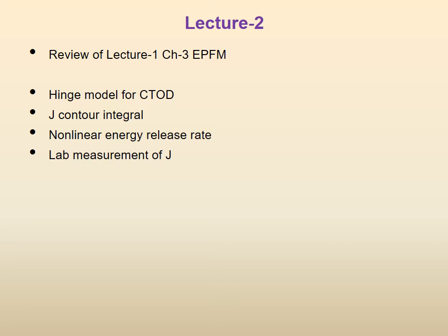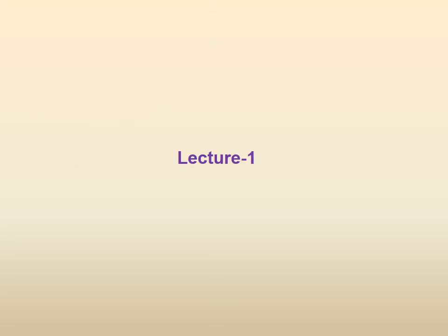We will of course start with a review of the previous lecture, and today the topics we will cover: we will continue with the hinge model for CTOD that we started last time. Then we will talk of the J contour integral, non-linear energy release rate, and probably, given time, lab measurement of J.